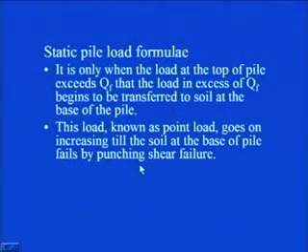In case Q exceeds the value of QF, the remaining load, that is Q minus QF, will get transferred to the base of the pile, and you can go on increasing the value of the load Q till the soil at the base of the pile fails by punching shear failure. So, whatever is the resistance of the soil at the base of the pile, that much extra load only you can put as point load.